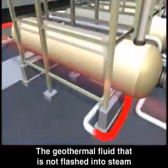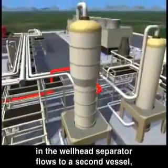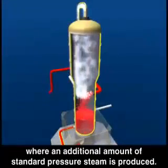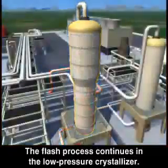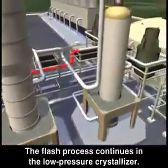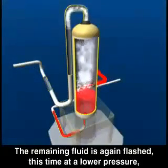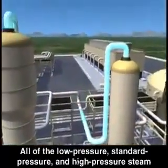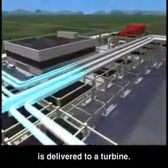The geothermal fluid that is not flashed into steam in the wellhead separator flows to a second vessel called a standard pressure crystallizer, where an additional amount of standard pressure steam is produced. The flash process continues in the low-pressure crystallizer. The remaining fluid is again flashed, this time at a lower pressure to produce low-pressure steam. All of the low-pressure, standard pressure, and high-pressure steam is delivered to a turbine.